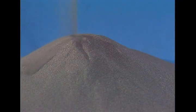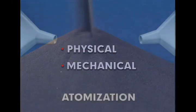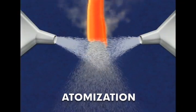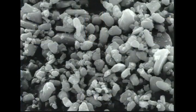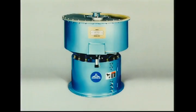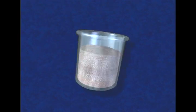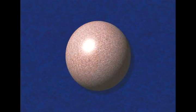Most metal powder is produced by physical or mechanical methods. Atomization by high-pressure water or inert gas is the most common physical method. Mechanical methods include milling in hammer, rod, ball, grinding, or attrition mills. Metal powder used for parts production can be a combination of various elemental particles or pre-alloyed powder.